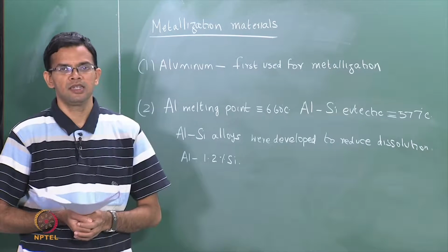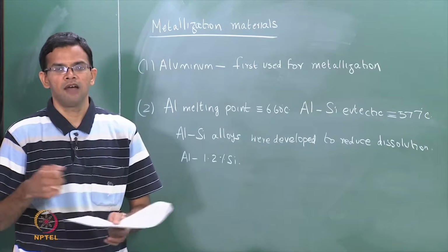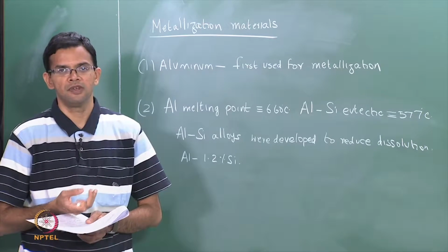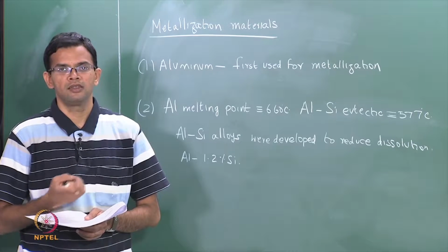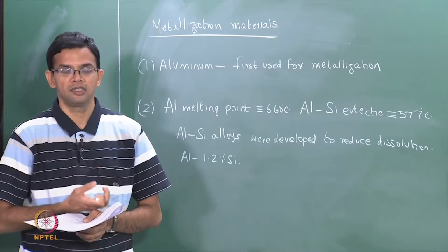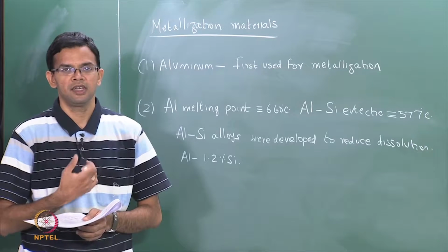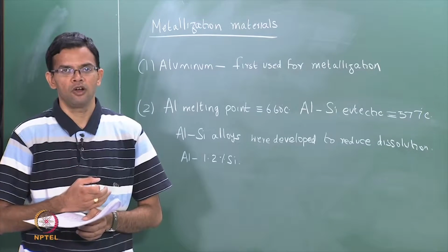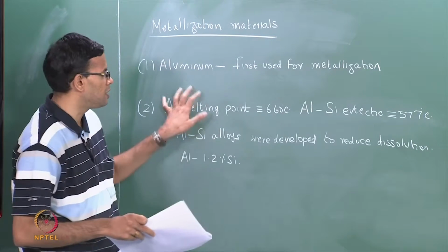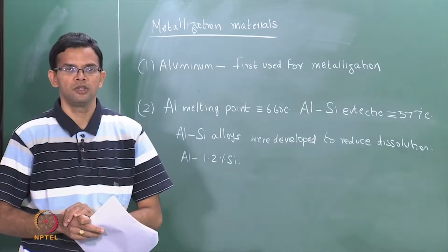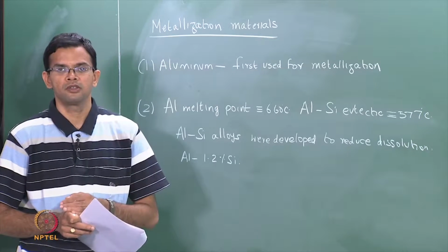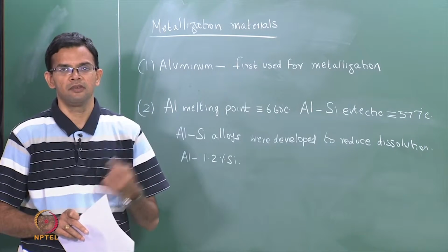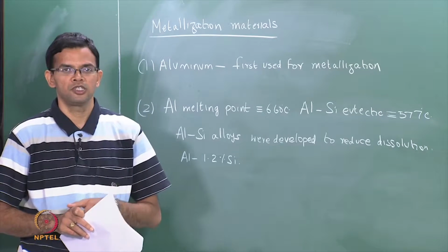So what happens in electromigration is that you have atoms which start to move under the application of an electric field. Also because you had thinner wires, you also had higher resistance, which means there was greater heating, so I squared R heating is higher, which again led to movement of material. So this is especially problematic in the case of aluminum, which has a low melting point. So this electromigration again led to cases where the wiring failed, leading to open circuits.